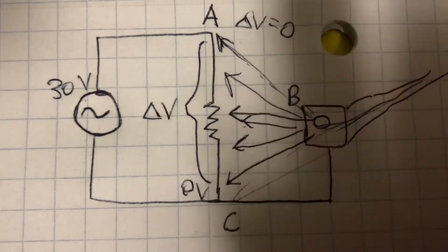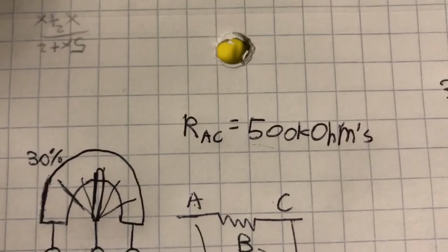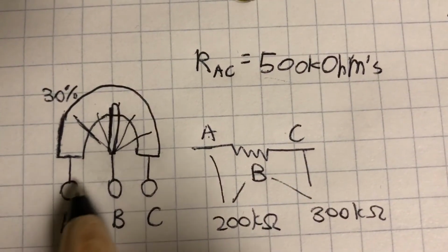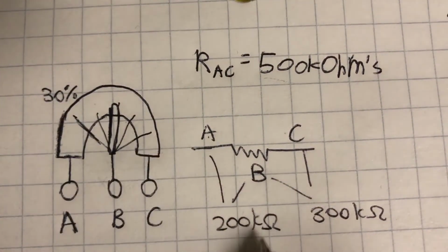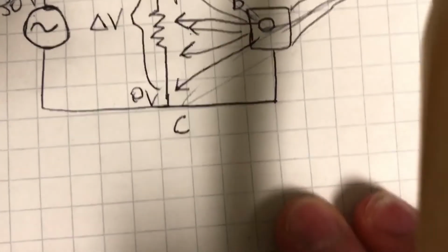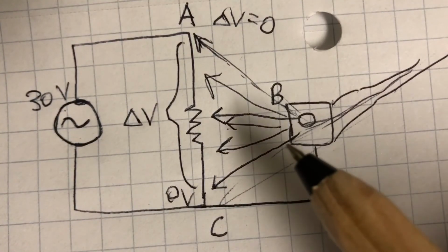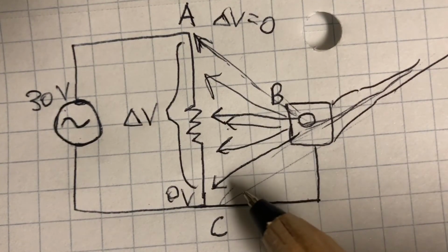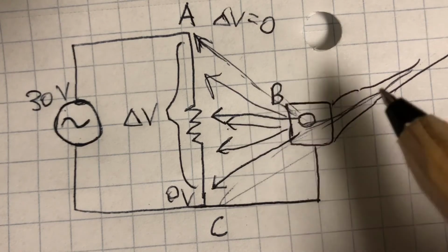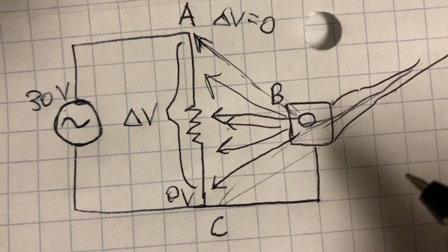And again, this is the same thing as what we talked about before, right? This whole idea of these 3 terminals and how they behave together, and how the sum of the resistances have to add up. Well, it's the same idea, except now we're going to be using it as a volume control, and that is how volume works. And hopefully that gives you a better idea now in terms of what is actually happening in the circuit when you're turning the volume. And we can now move on to tone.